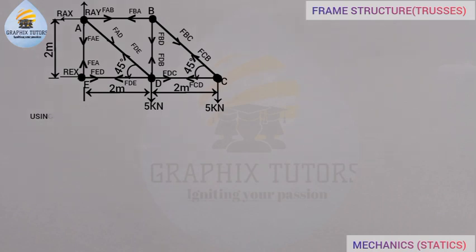So, using joint analysis, we need to consider each joint, and a joint is a point where two or more members meet, right? And for you to take a joint, there is one thing you must put into consideration. The unknown forces at that joint must not be more than what? More than 2. The unknown forces acting on members at that particular joint must be just 2 and below, at most 2. Is that okay now?